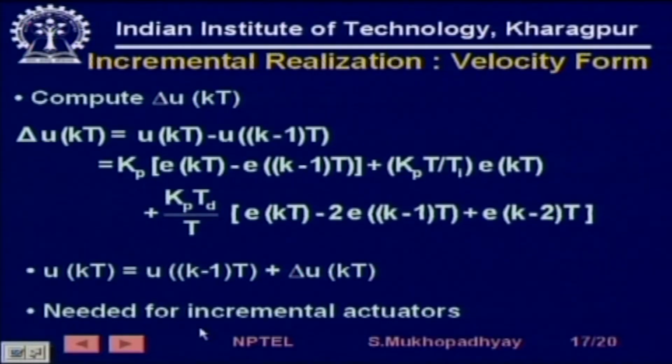And there are also some kinds of actuators, let us say like step motors, where the actuator itself integrates the output. So, this summation you need not give, you just keep on giving the delta u's, and the actuator will gradually move and will continuously add it. So, in a position control using, let us say, a stepper motor, it is very convenient to give the delta u's. In fact, it is the delta u's which have to be given, and therefore, the PID control has to be implemented in this form.